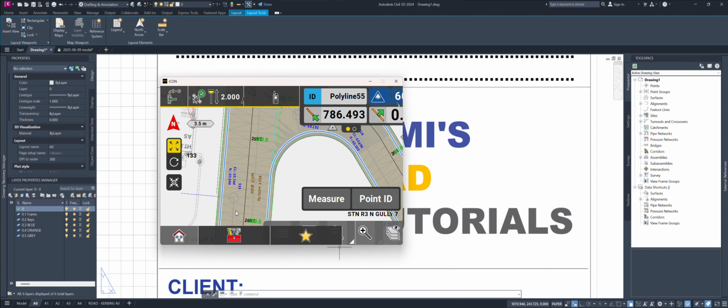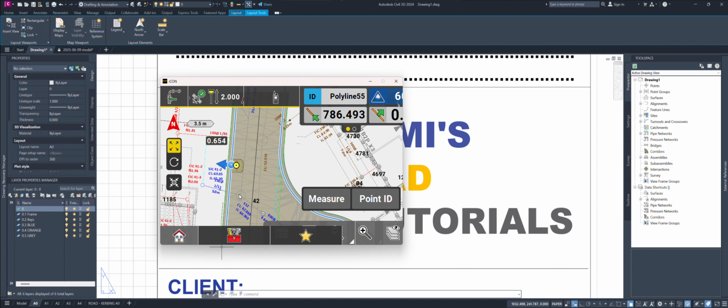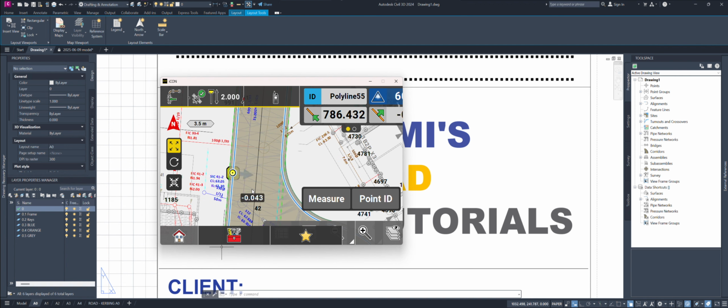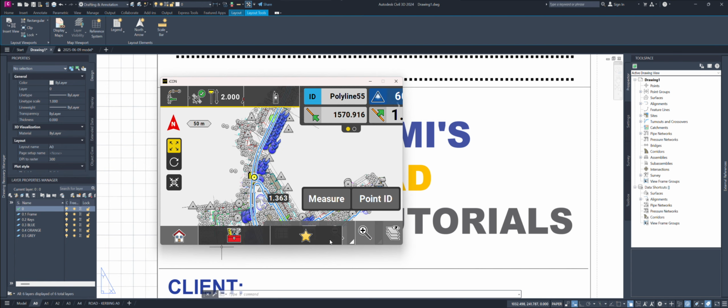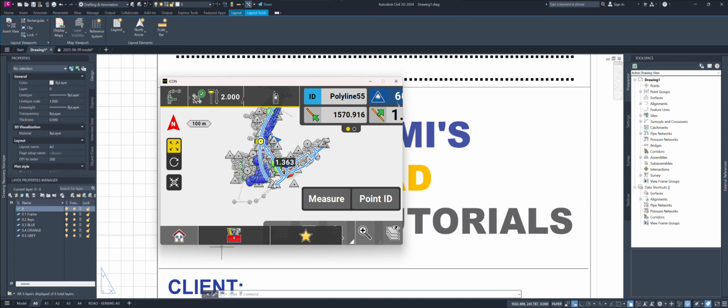Okay, so like I say, let's say we're setting out roads and stuff like that. Every time I move to the left channel, I'm snapping directly to it, and then if I move to my right channel, I'm snapping again directly to my channel. So the way to do this is by looping your 3D string all the way around. In my case, I can show quickly how it looks like. You can see I managed to loop my roads all the way around by connecting them all together.